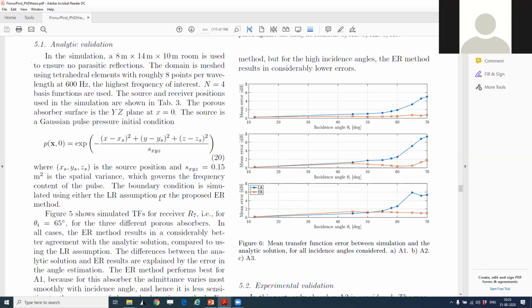So how would you go from this excitation to a more realistic one? Right. I think it depends on what you want to do. If you just want to estimate, for example, the reverberation time of a room, then this is actually pretty good. It's a uniformly distributed source, and you're just assessing the relative energy decay at different frequencies.